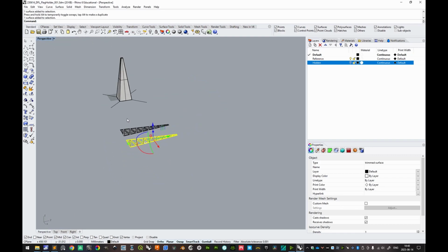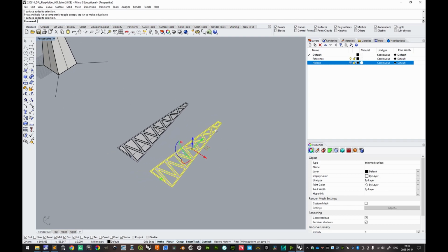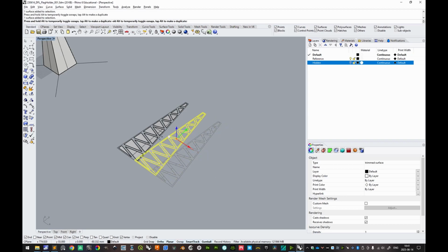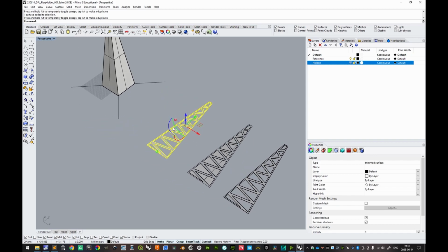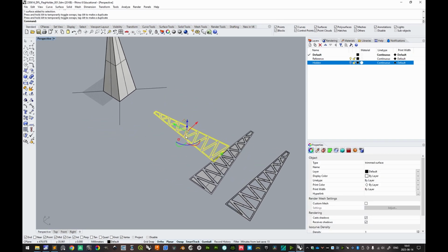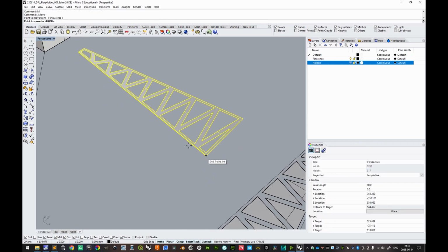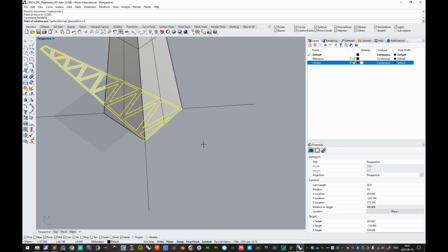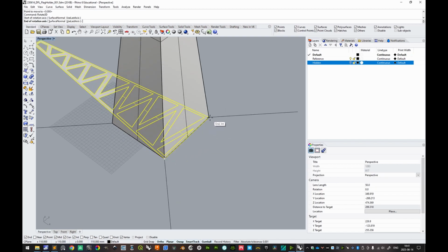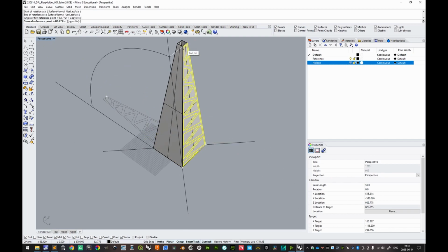And we are in the perspective viewport, so we can make sure that we reposition it here. We could actually make a copy of it. If you have the gumball active, as previously shown here, then you can simply hold Alt and drag. And you see the plus icon that makes sure that it's a copy of the original. And then we can rotate this. We first make sure to move it to the correct position here, like that. And then we rotate it 3D and start with selecting the rotational axis like that, and then the first point there and the second point there.